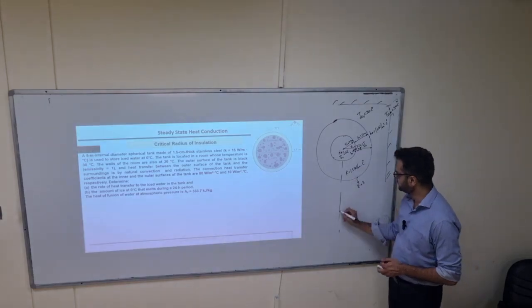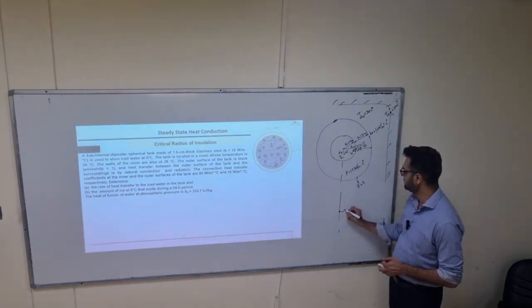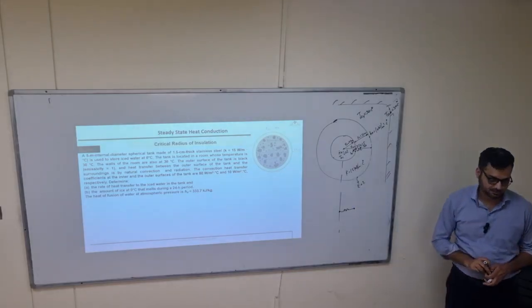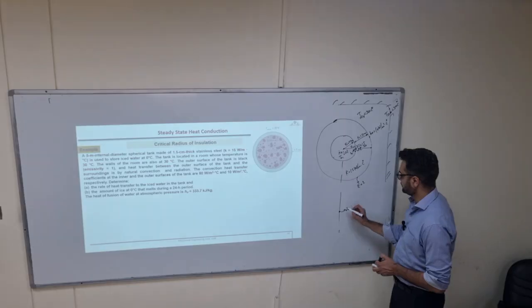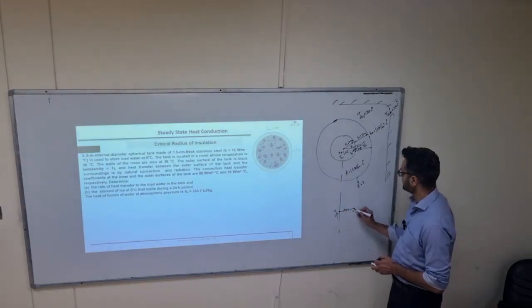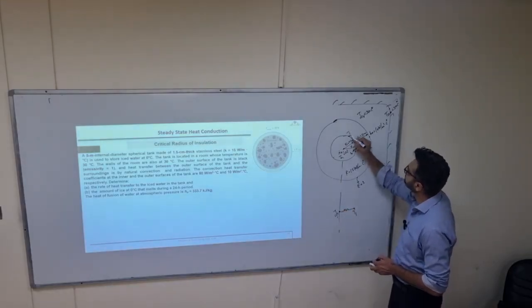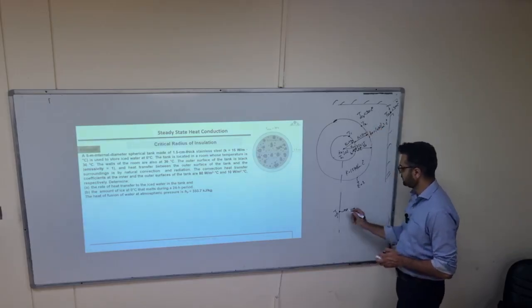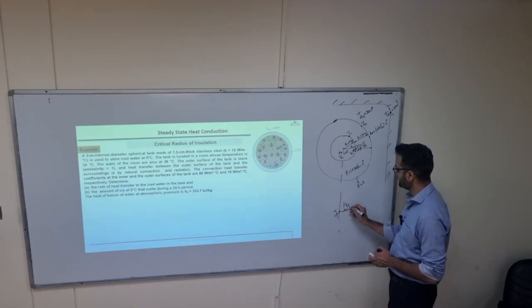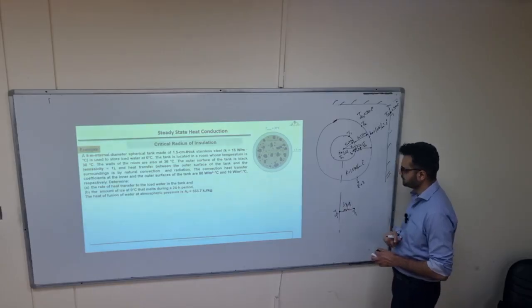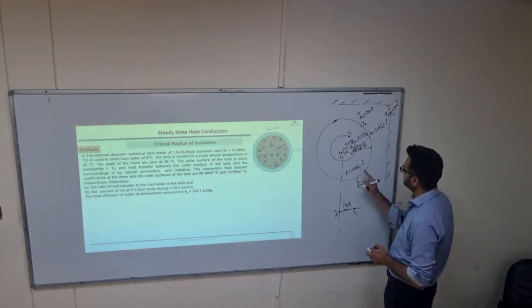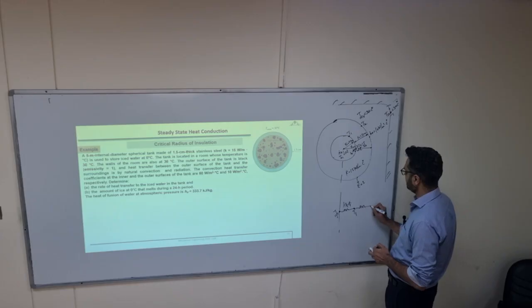So starting from the fluid, first heat transfer resistance will be what? Here Hi is given. Convection. Okay, so here it is T infinity 1 and this will be T1, and this will be T2. So from T infinity 1 to T1, it's 1 over Hi into area, Hi Ai of the sphere. Next, yes, it's conductive, and that is sphere.